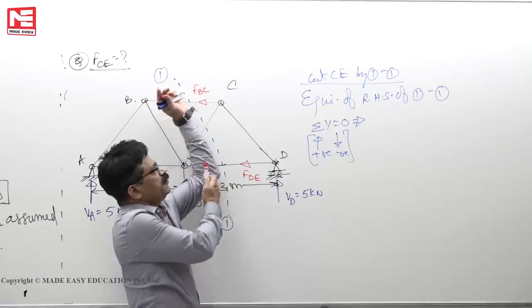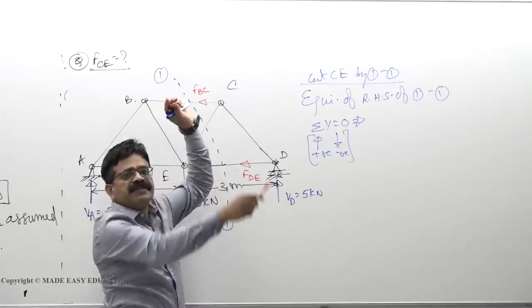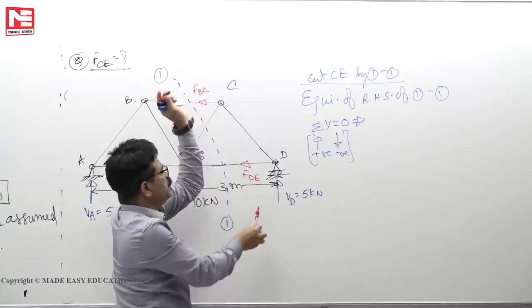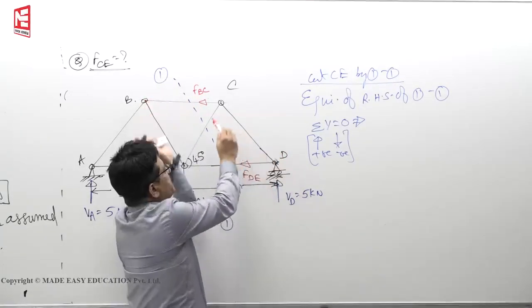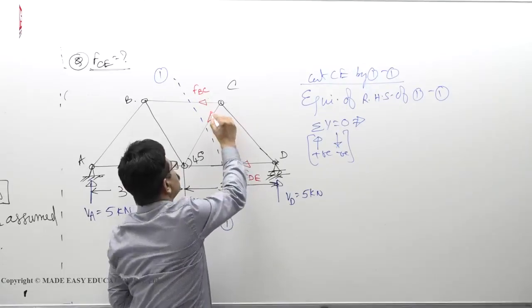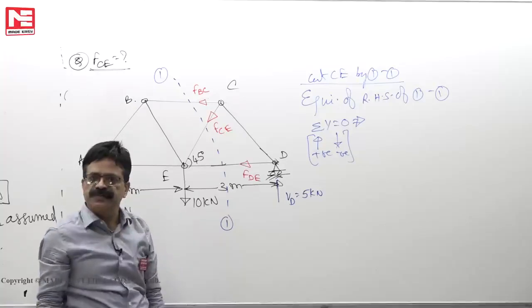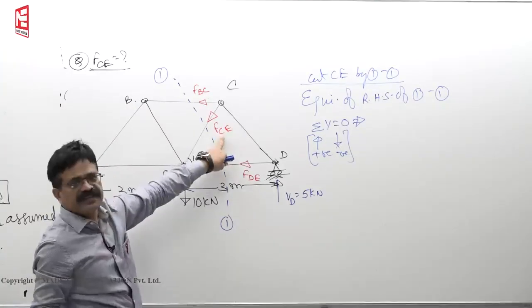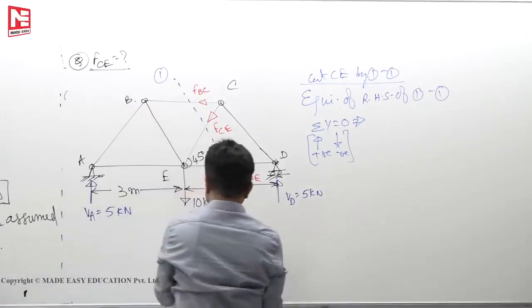Cut here, look right side. See, these 2 horizontal forces will not have vertical component. So they don't come into picture if you write sigma y equals 0. So if this is upward force, to balance this upward force, it has to be downward only. So the question of negative sign also will not be there. So like that we will fix the correct direction for this one. These 2, any direction you put it, it will not matter at all.